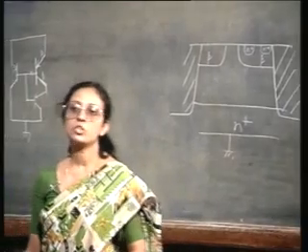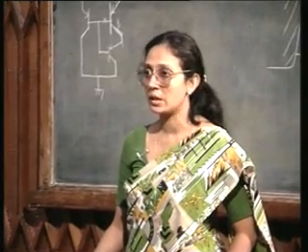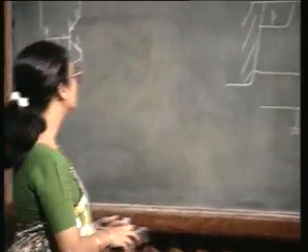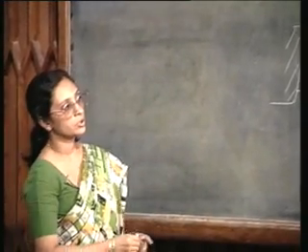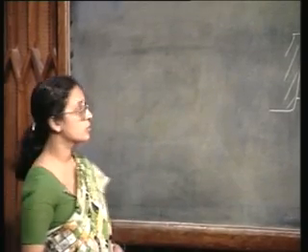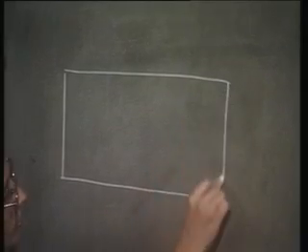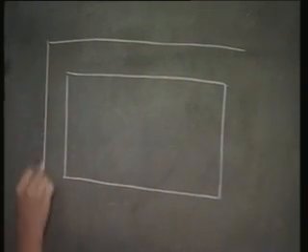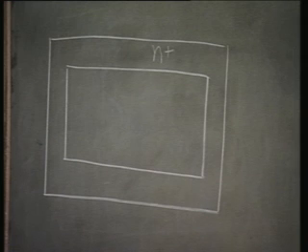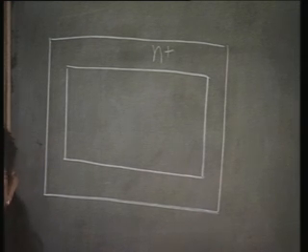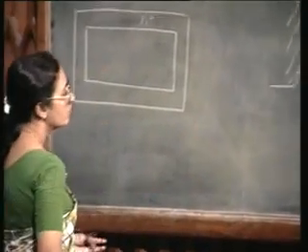If we look at the top view of these two I square L designs, that is one using N plus collar and the other using the oxide isolation, the difference will be clearer to you. Let us first talk about the top view of the mask, where I use the N plus collar. This is the active region and I have N plus collars surrounding this active region. This is my N plus collar, right. And in this active region I have the consecutive PNP regions.